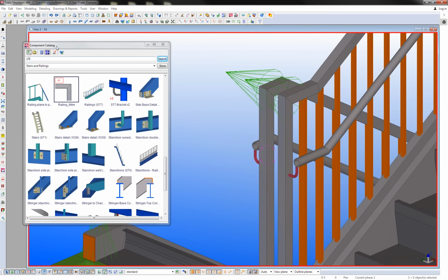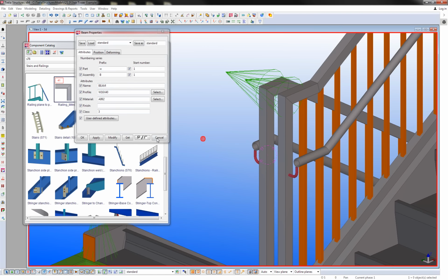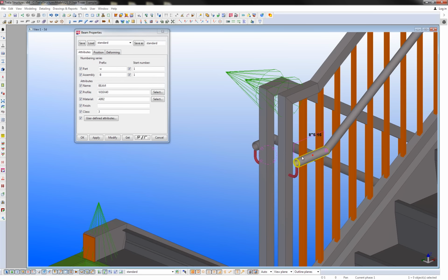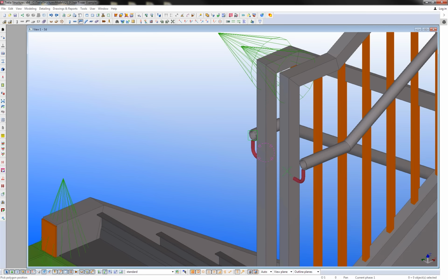And then I can add a return like I did at the lower section. So again, I'll open up my polybeam tool. I'll simply go ahead and take the properties from one of the current grab rails. It's very easy for me to just throw this in.